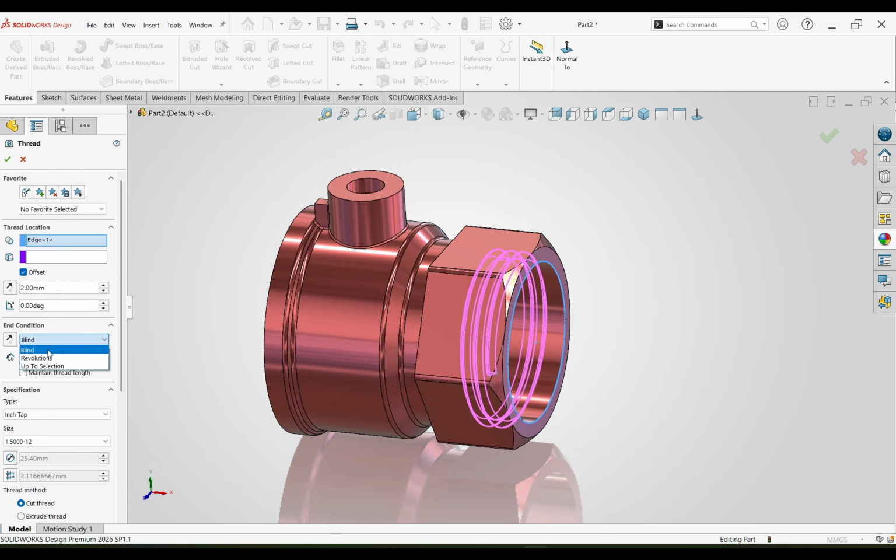Select front plane, draw a hexagon and the inner circle. Make it horizontal. It will be 25.4 and the total distance 30 mm. Now extrude it. The extrusion value 40 mm and OK. Isometric view.